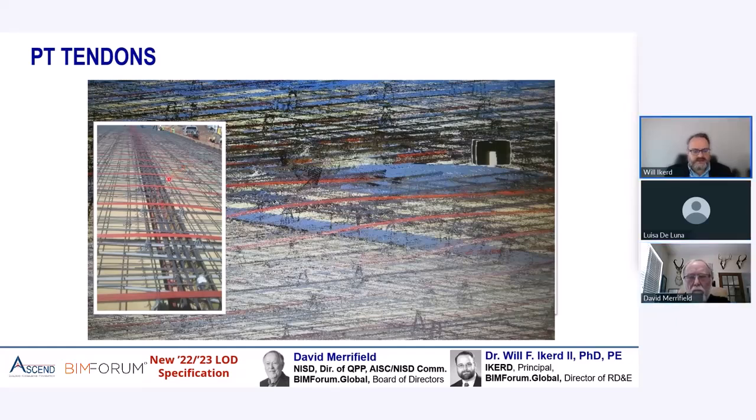In that condition, you're really dealing with moving formwork from people walking on it and throwing rebar around and tying steel and blowing off dirt. And so that's why there's so much noise in this laser scan data. It's because the scanner is vibrating from ambient vibrations. So the tolerances are not going to be anywhere near the published tolerances of the scanner. These scanner published tolerances don't assume you're on elevated deck formwork that's being shaken while you scan. And so specification requirements need to identify that.